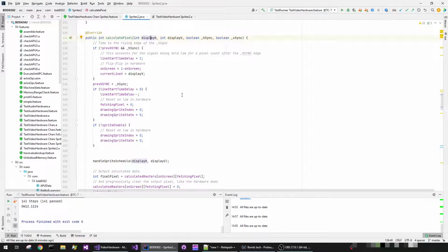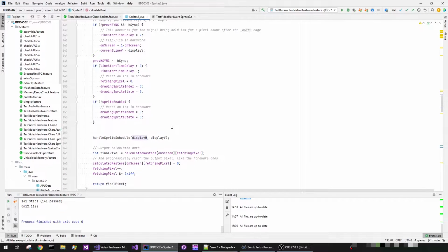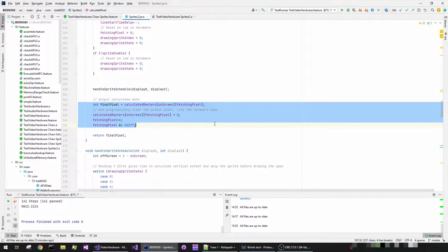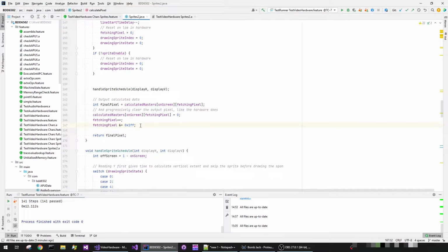Basically, I just started by using a similar kind of logic that was found in the original sprites layer, where I have the notion of two sprite Scanline RAMs. While one is being displayed and cleared from the calculated pixel values, the other one is having the calculated sprite values stored into the relevant position in the sprite Scanline RAM.